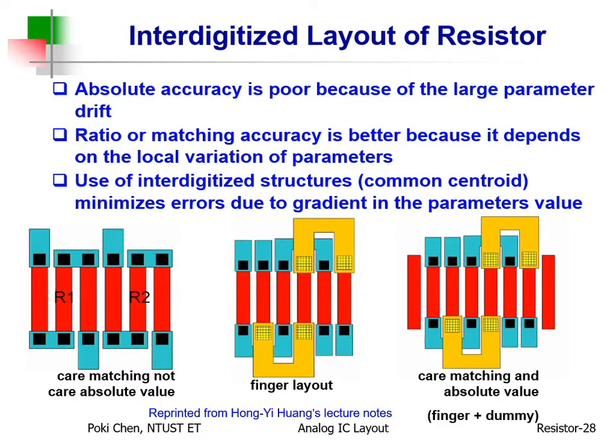Then, this is some kind of interdigitated layout for the resistor. Yeah, you need to mix them up. That's it, to achieve better matching. That's it. All right.